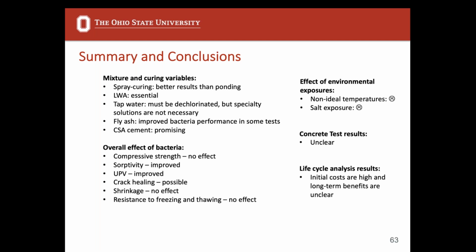We also saw that crack healing was possible, at least in our samples that were not exposed to high and low temperature and salt. We didn't really see any effect on shrinkage or freeze-thaw. But the scale of this system to real work was pretty disappointing. Non-ideal temperatures appeared to mitigate any effects that we would see, as did salt exposure. And initial costs are quite high.